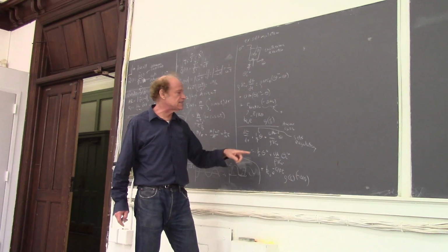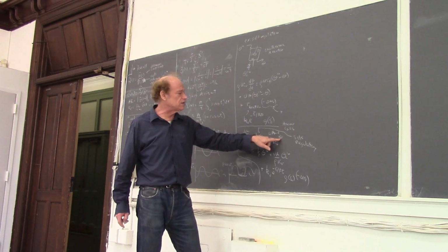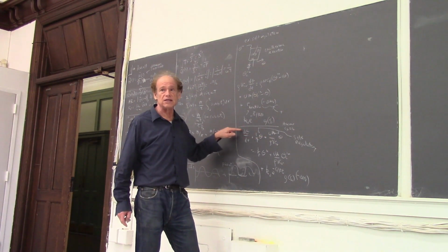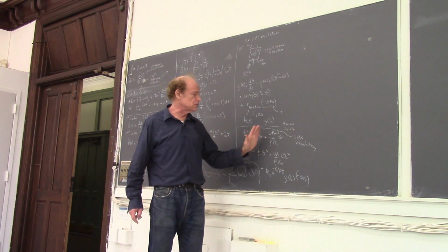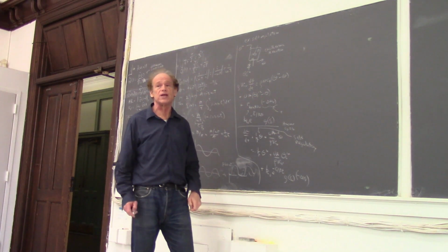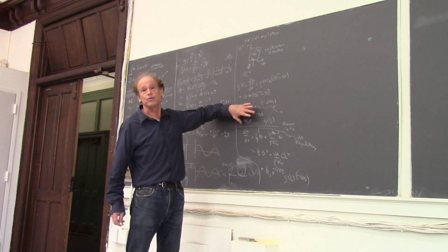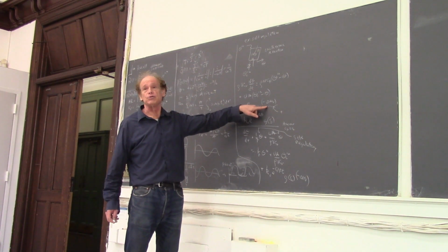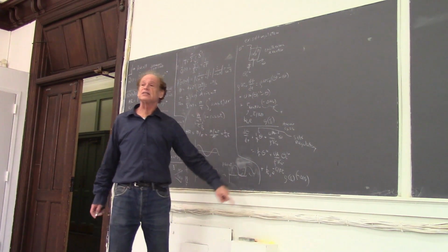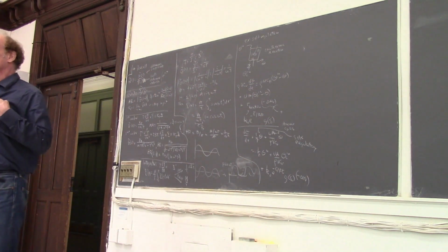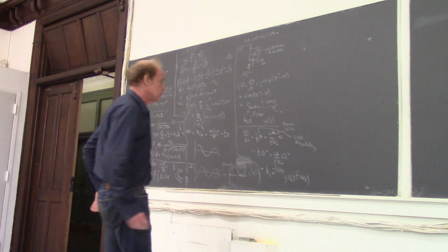Notice that when theta goes up, these two terms make d theta dt go down, because if they were on the other side of the equation they came with the negative. As theta goes up, the rate constant goes up, the rate of reaction goes up, and I produce more heat. So this is the opposite of self-regulatory, it's self-enhancing.